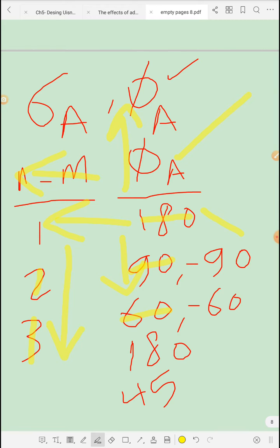So as the number of asymptotes increases, some of the asymptotes will be directed to the right hand side, and this shifting to the right hand side means that the root locus is directed also to the right hand side. If n minus m is greater than or equal to 3, there must be a value of k beyond which the system will be unstable, crossing the j omega axis and moving to the right hand side of the s-plane. And this is what I need you to remember from the previous chapter.